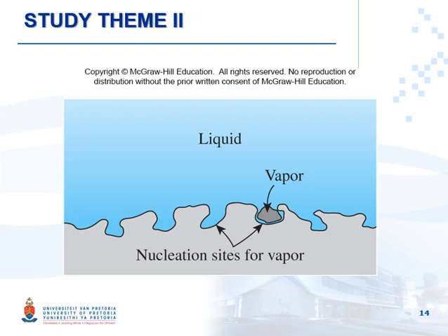The second one is that the surface roughness won't affect the maximum heat flux, which is happening at point C. Since we always design things for point C, we achieve point C, and that point will stay the same regardless of the quality of the surface. So just think about it.